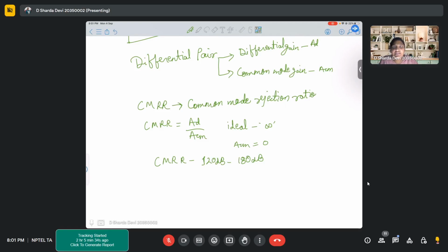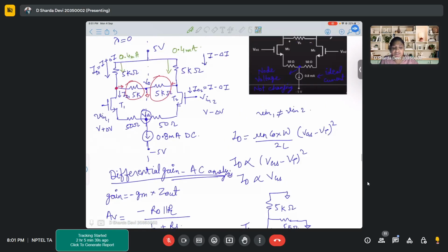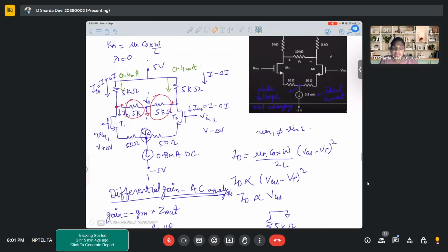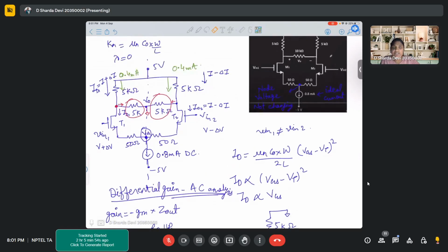So we always see the op amps as sort of a black box, but actually the circuit which is inside the op amp is somewhat like this. It is even more critical because all the components are just transistors. So it is made up of an all-transistor circuit. So there the idea is at the very beginning stage you can use one differential stage and after that you can use multiple single stages or cascode or other stages to attain the gain. But for noise cancellation, the differential stage is very important. So first focus on noise rejection through the differential stage.